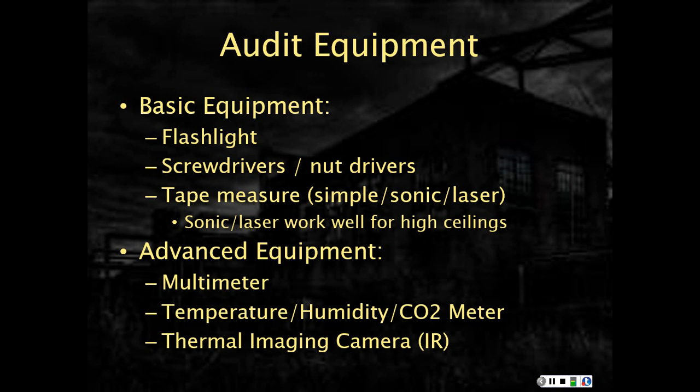Under advanced equipment, it's always nice bringing a multimeter to check voltages, amp draws on things. A side note under a multimeter would be some sort of simple watt meter that you can plug in and actually plug small pieces of equipment in to get an idea of what kind of wattage they use. That's always handy.